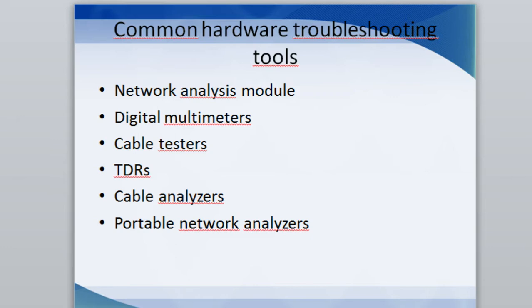This is what most of them do, but again, if we get more advanced or more sophisticated cable analyzers, we can find some of them that can measure the distance to a performance defect, that can identify corrective actions and graphically display crosstalk and impedance behavior. And most cable analyzers have PC-based software, so we can see the results that it is producing on the PC.